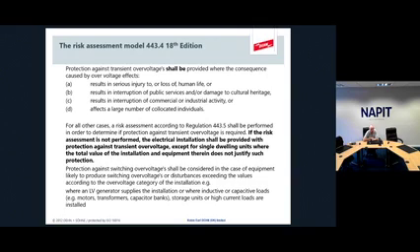And then in bold, I've highlighted that if you don't do the risk assessment, the installation shall be provided with protection against transient overvoltages. So it's the case now that you do not leave an installation at risk if it warrants having SPDs fitted. And there's a further exemption, and that's if you've got a single dwelling unit where the total value of the installation and the equipment therein does not justify such protection.